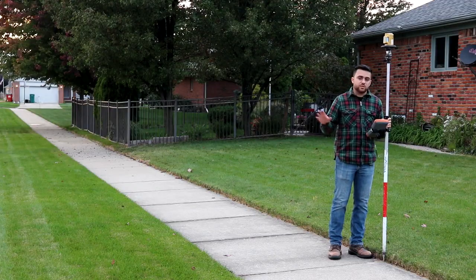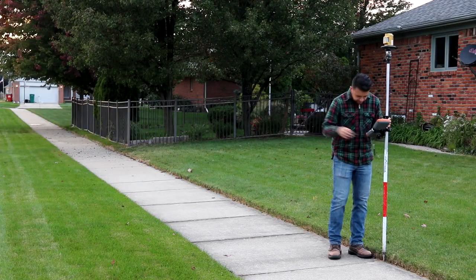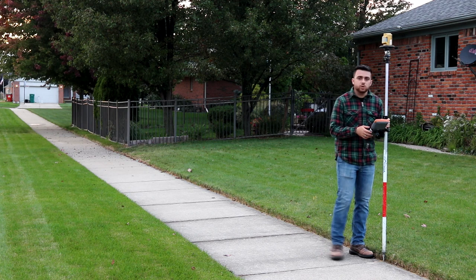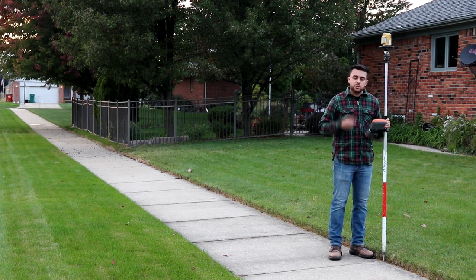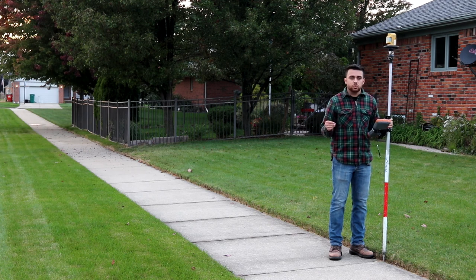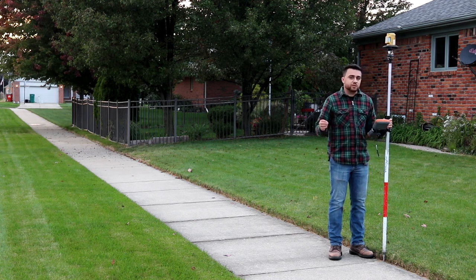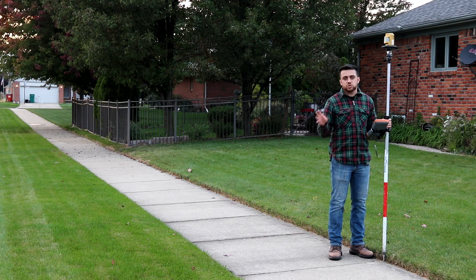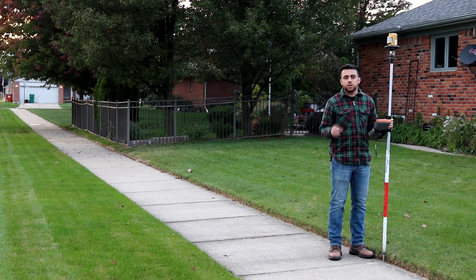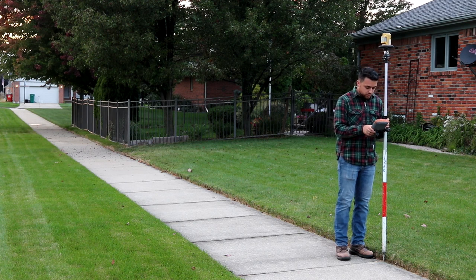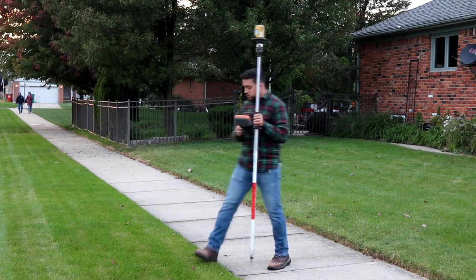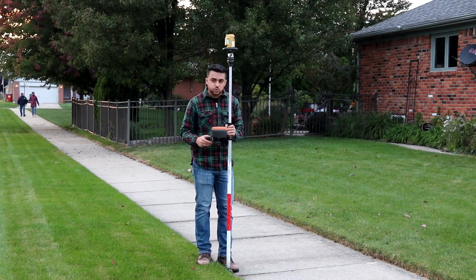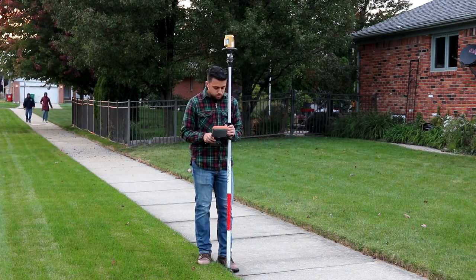Now we're going to be starting our topographic survey here on this sidewalk. The sidewalk is made of concrete, so I'm going to go ahead and call this concrete. And in the Carlson software system, denoting a number after your code indicates a beginning of a line. Your software might be a little different, so consult your software manual to figure out what the code needs to be to begin a line. So I'll do concrete 1. Great, and start a new concrete line. So this will be concrete 2.